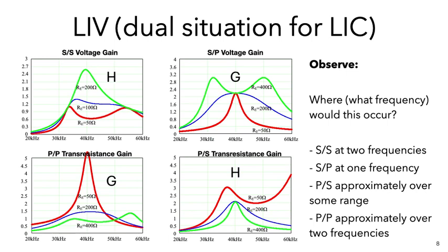Now, you would use G as the transfer function corresponding to the optimal efficiency point, and H as the transfer function which does not correspond to the optimal efficiency point. In practice, usually there are two operating frequencies, and the upper one is preferred because of the possibility of generating zero voltage switching with slightly inductive input impedance.